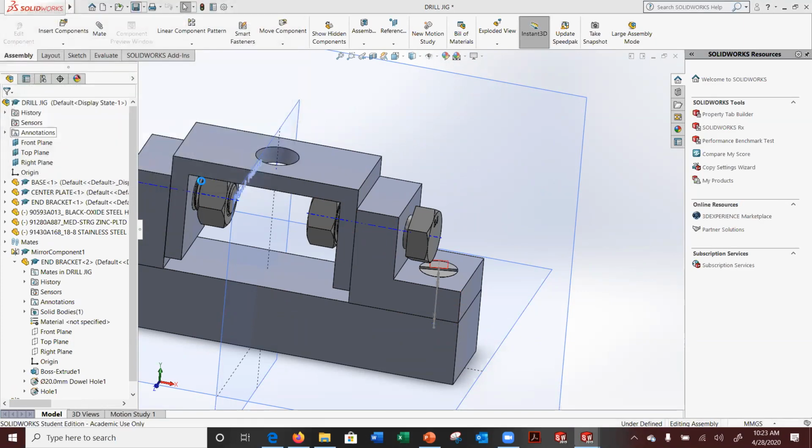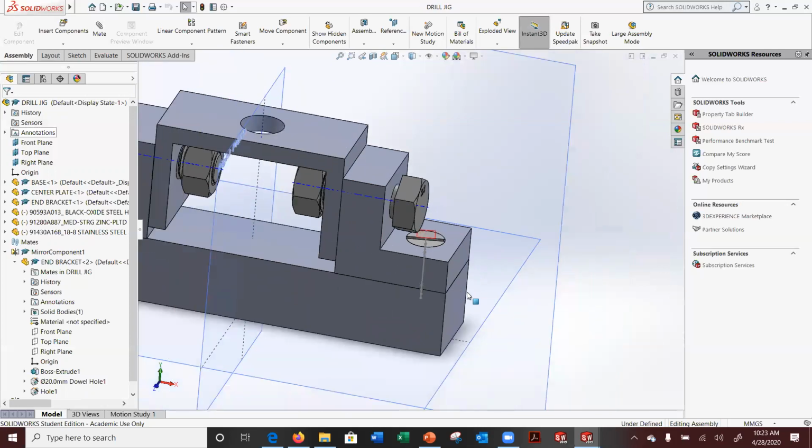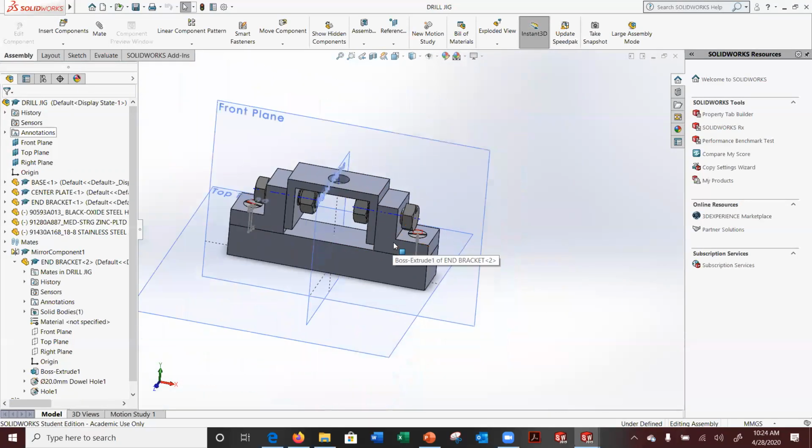I'm doing a save all to make sure I save, and save often. Please remember this. This is very important. This is how to fix components in an assembly. Don't go and open that file and then edit that item separately of your assembly. Edit everything in assembly. So the lesson of the day: the sooner you start your assembly file when you're working on your final project, the better, because that's how you're going to be able to tweak your parts to make sure they're correct. All right, guys?